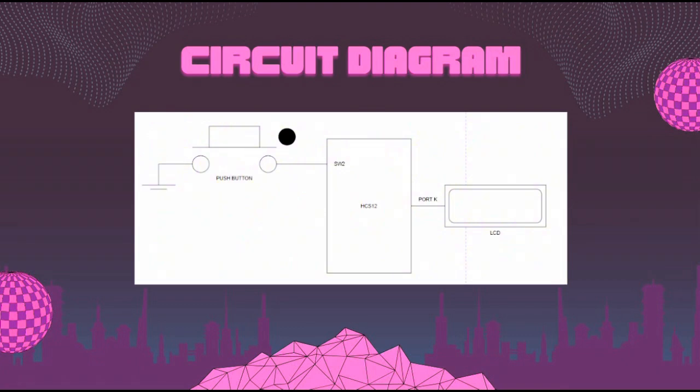The HCS12 microcontroller acts as the brain of the circuit. It performs several tasks, such as detecting button presses for switch 2 and switch 3, managing the internal timer functionality to measure elapsed time, sending the measured time data to the LCD for display, and activating the buzzer when switch 3 is pressed to provide feedback that the timer has stopped.